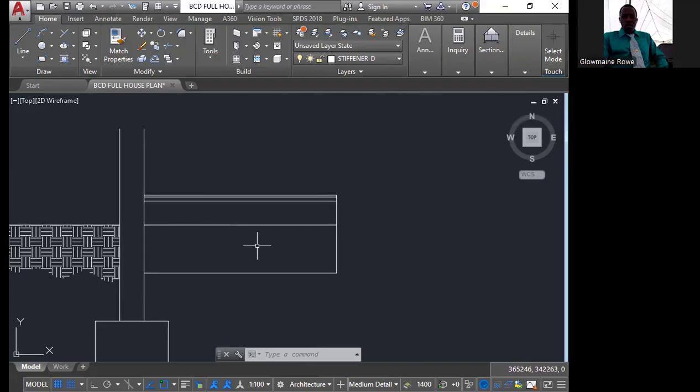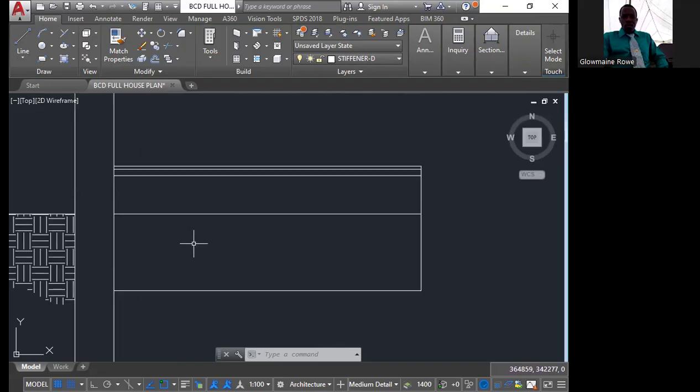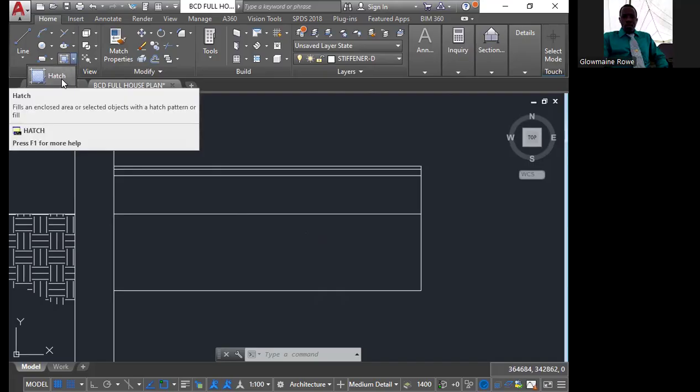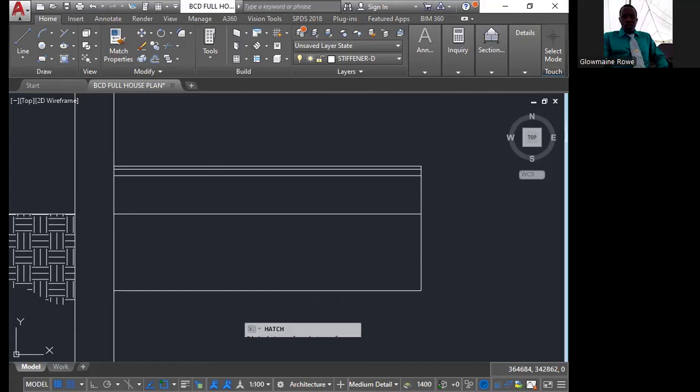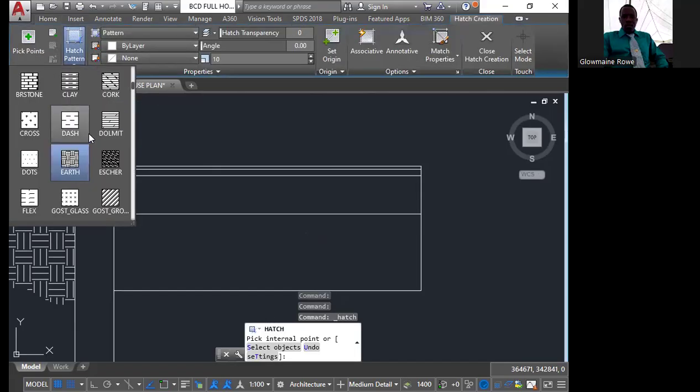And inside, these are the layers that make up your floor. For those who have experienced seeing persons work on site when they are doing the floor, what is the first thing that they put in? Stone. Yes, then pack it with stone. So for this first section here, we're going to use the gravel hatch. It's stone, you know, but in AutoCAD, it is the gravel hatch. So you're going to look for gravel.